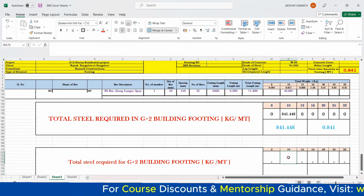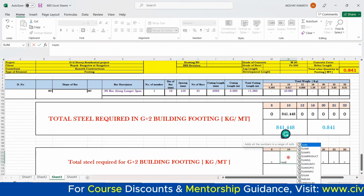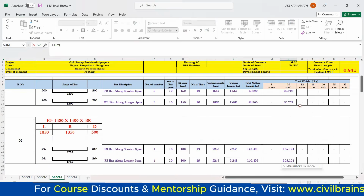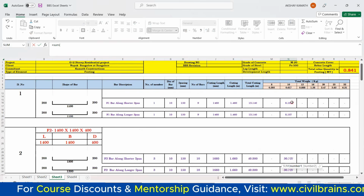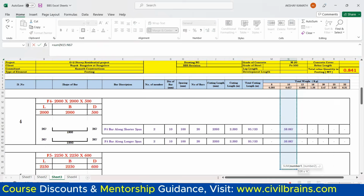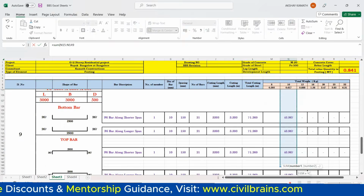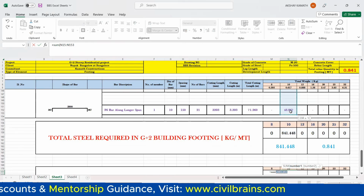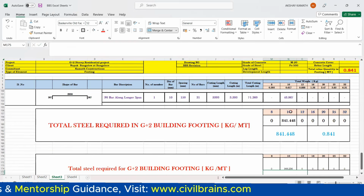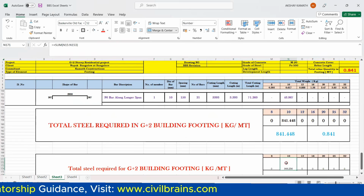Now for the 10 diameter, what we'll do, we'll select plus sum and open the bracket, and then go on selecting from here. Okay, we'll start from here. This is 10, no? So drag it in this way so that all the values under the 10 diameter bar are selected. Okay, up to here. And then close the bracket, hit the enter button. So done. So what happened this time? It's coming 966.